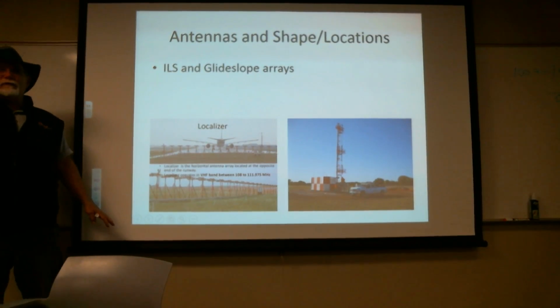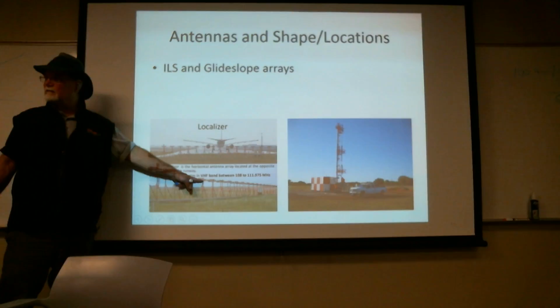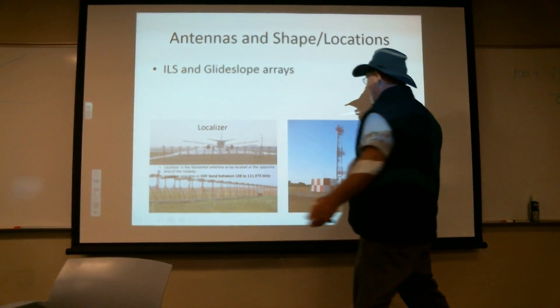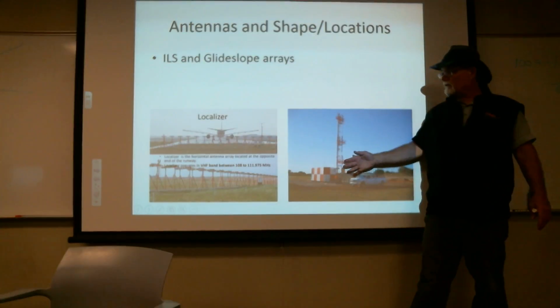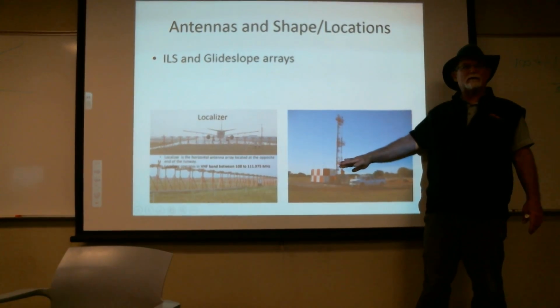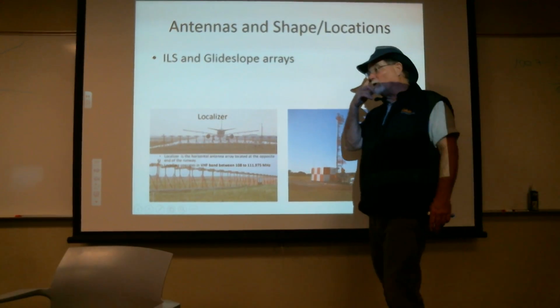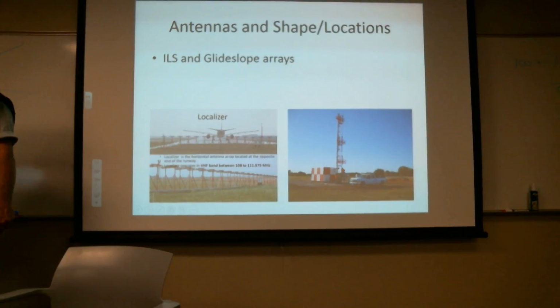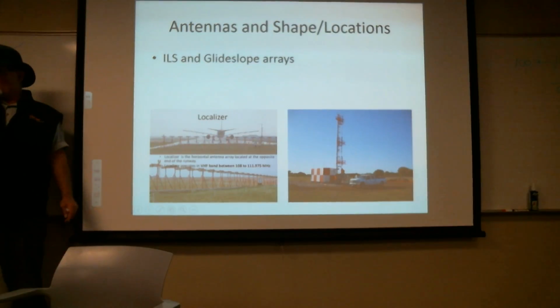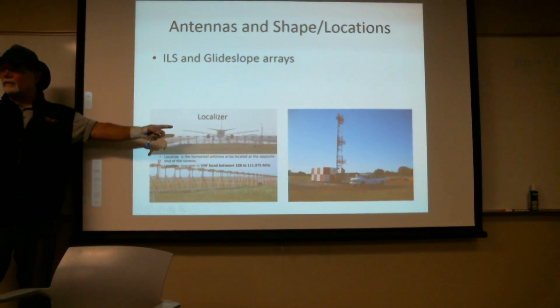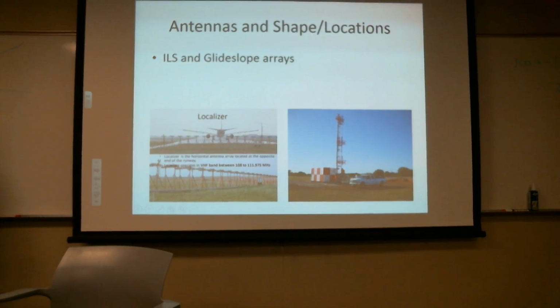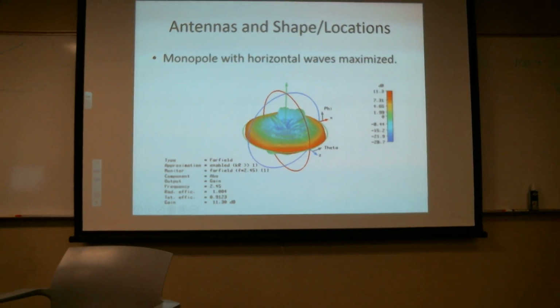Okay? And the reason we need to do that is because when I tune to this, I'm also going to tune to a preset frequency for the glide slope. So for every frequency here, it's in a completely different band, but I have a unique frequency dedicated to glide slope. Those are all pre-arranged. That way you're not having to dial several different radios. All you're going to do is dial one radio. If it happens to be a general navigation frequency, then that's the way it's going to work. If it happens to be one of these frequencies, not only is the data the radio provides to the meter going to be different, but it's going to pair to one of the glide slope frequencies, the one that's paired to it. Okay? I think I said that.